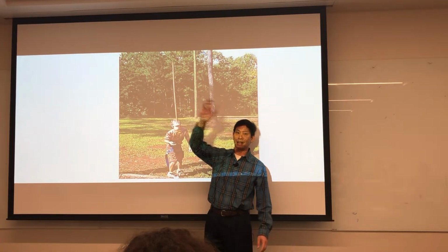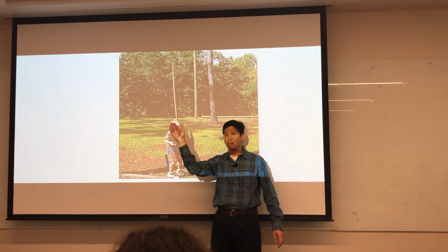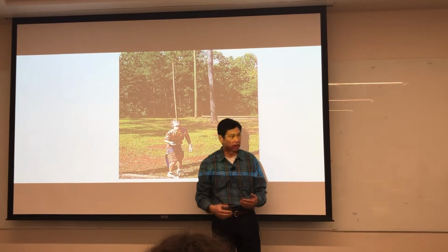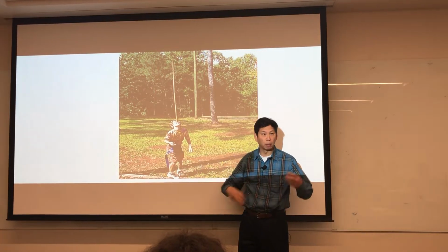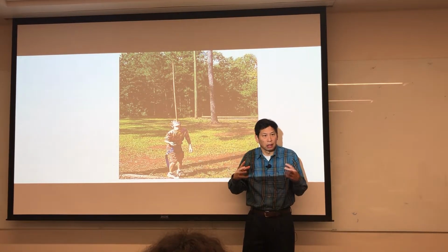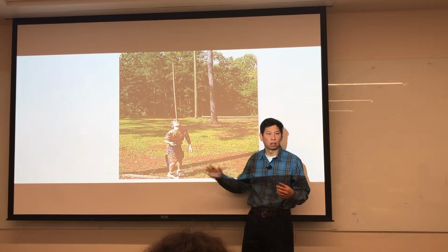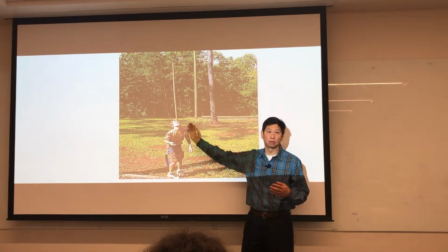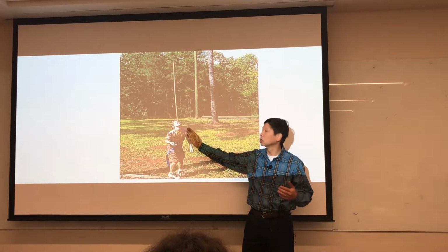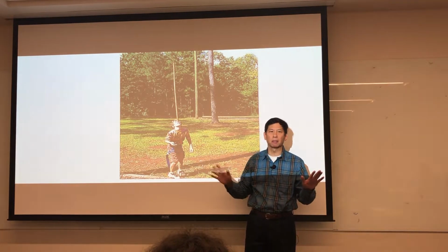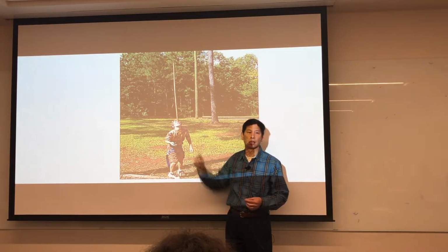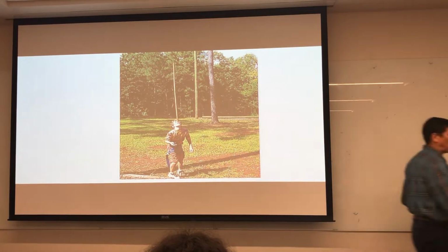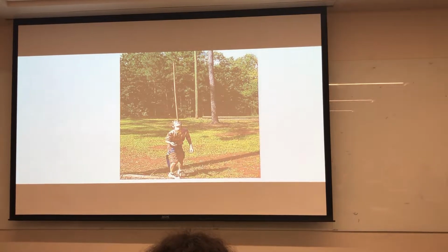inherently nonlinear. You can imagine there's sine of the angle involved as gravity works on it, so it's nonlinear. There's the reaction time of the human body. There's a little bit of delay there. For example, if you're drunk, you're going to have a much more difficult time than if you're not drunk. So we're going to ignore some of those issues. We're going to ignore the nonlinearity. We're going to assume that you can instantly move this thing around, and we're going to work with a simplified model. And so the simplified model is this.